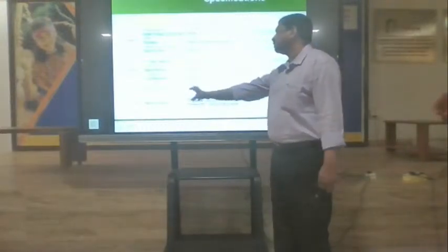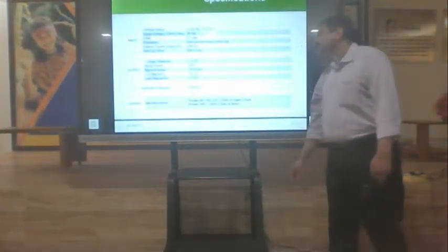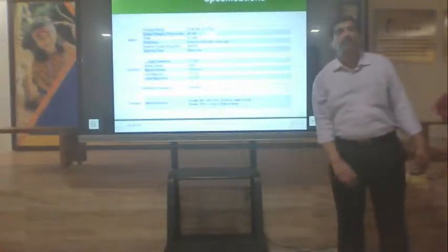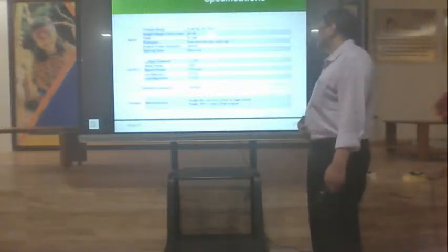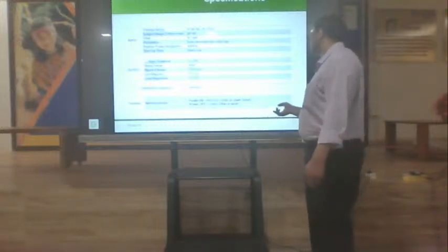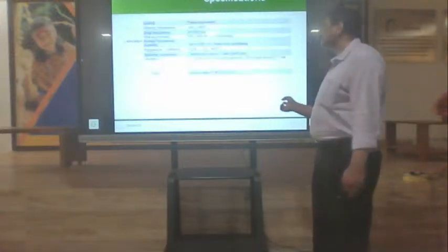Here again you can see the typical switching frequency is around 400 kilohertz. It is going to be a high frequency. And then these are all the functional controls. You have a remote control pin through which you can give a TTL signal to switch it on and off. To make it switched on, this pin has to be grounded. If it is left open, it will be in off condition.